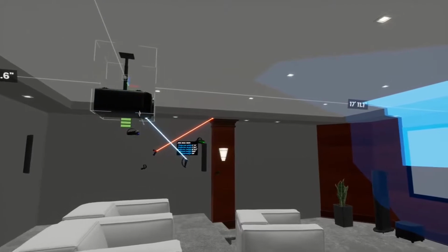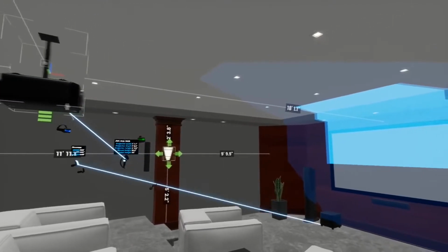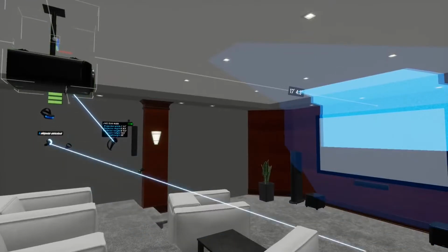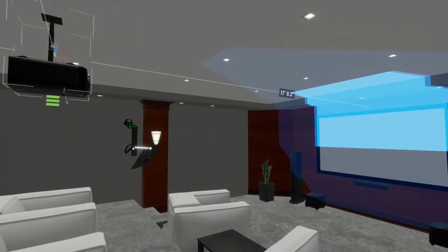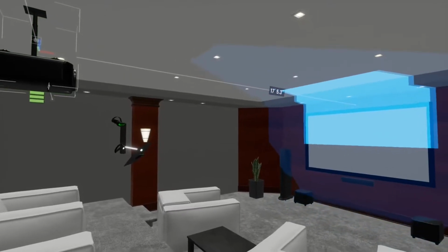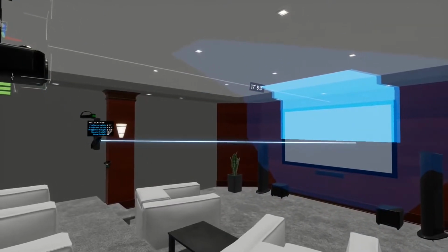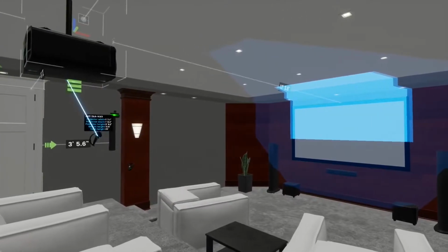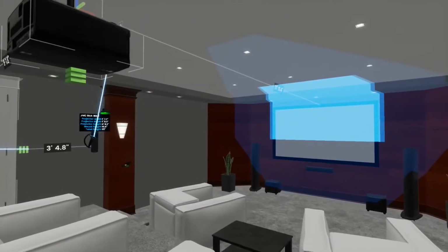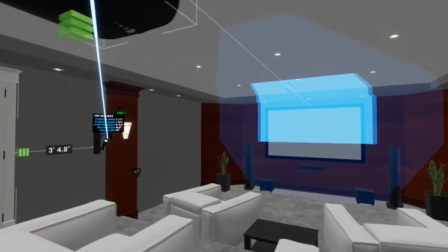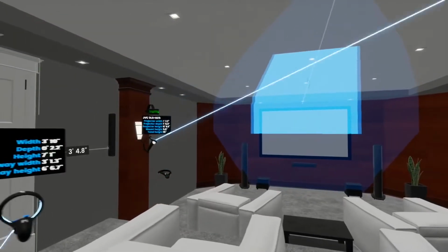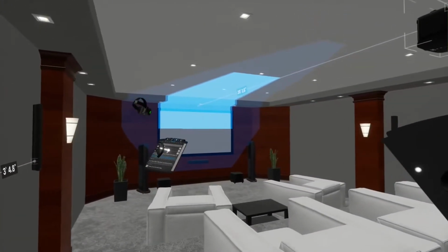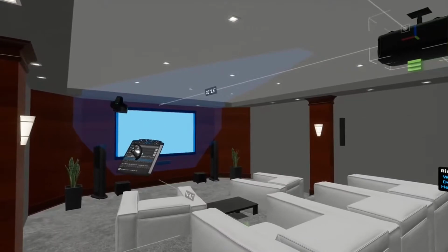The nice part is we're doing it in the context of the room, and so we can see exactly how this projector is going to perform. We know what its zoom and horizontal and vertical shift capabilities are, and I'm also going to switch this. We'll keep the 16:9 for now and see how well it works. Basically, we can put the projector where we would like to put it in the room, and then see if zoom and horizontal shift will get us where we need to be. And it looks like, yep, it's just about perfect.